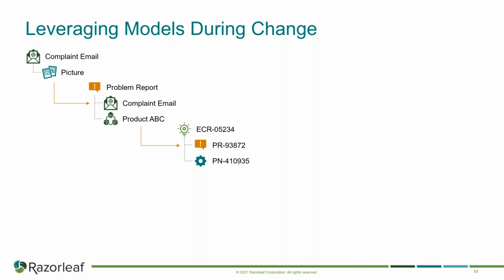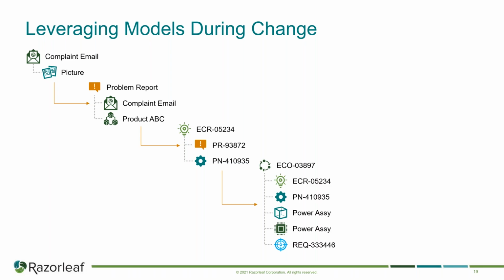Okay, that's all logical, I think. And engineering change requests get looked at, they get decided: do they go on hold, do they get moved ahead, that kind of thing. But frequently, when it's something urgent, like somebody burning themselves on your product, it's going to get turned into an engineering change order where you reference the change request, the investigation that was done, the decisions that were made about how we would resolve the problem and what the fix might look like, and connected to what needs to be fixed in the bill of material. And then also we tie in what needs to be changed. Well, clearly we're going to have to change that power assembly, maybe the packaging on it, maybe the components that we use. We need a bigger cooling fan or something.